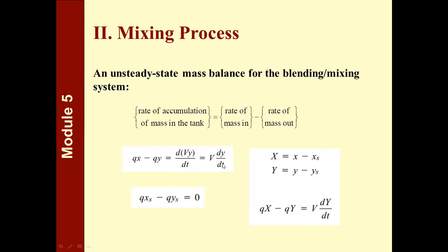When you evaluate, just like the way we derived the transfer function for a liquid level system, you will evaluate this original model DE at steady state. So at steady state, there won't be any changes in the concentration of the liquid inside the tank. So the right side becomes 0, and your variables in here will be represented with a subscript S, denoting that these are variables at steady state.